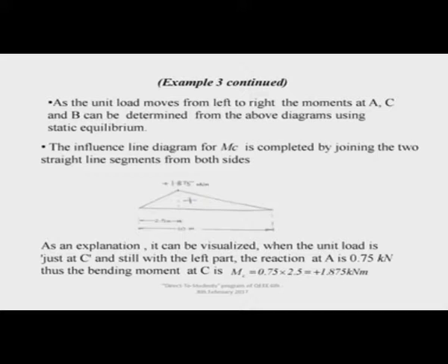What we mean to say is that we are sitting on the structure, and the unit load is moving over us, and I am trying to feel how the bending moment where I am sitting changes with the location. You can check the maximum will be here because the structure will bend most, and it will be 0 where the load is on the supports because the load will be directly transferred to the support.